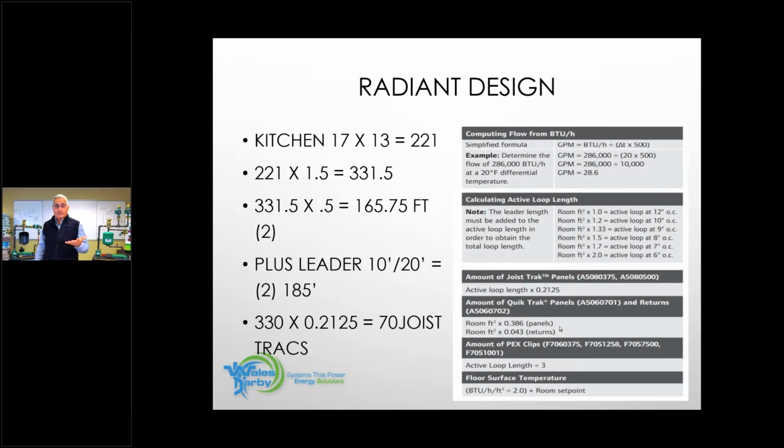All right. But I'm glad that person asked that question, because radiant ceiling is another great option. If I've got a lot of traffic, meaning a lot of furniture, cabinets in that kitchen, maybe an island, that takes away available floor space as a heating source. This works out really well in bathrooms, especially second floor master bathrooms.